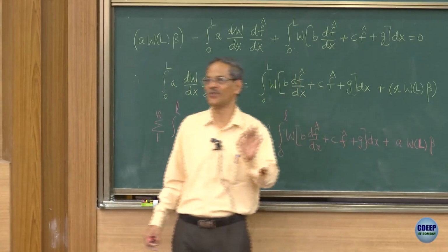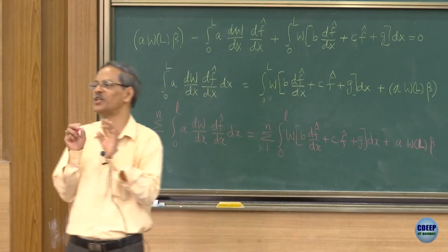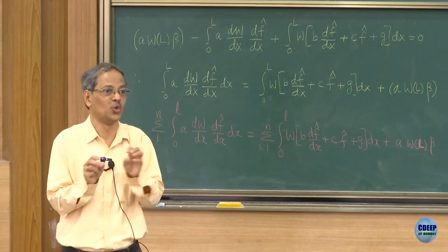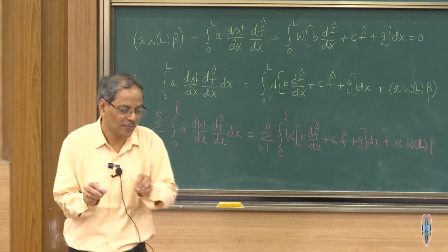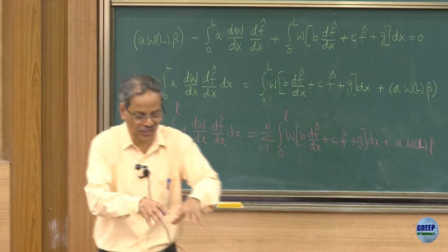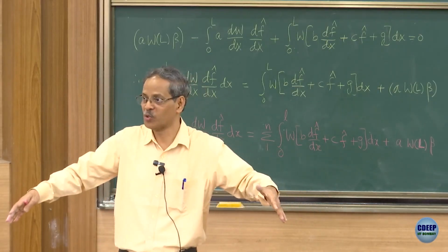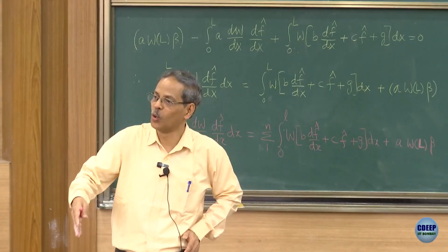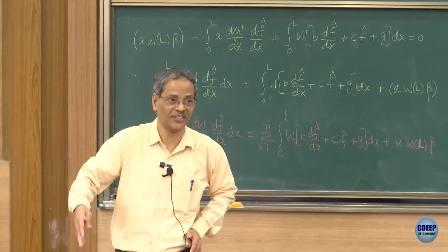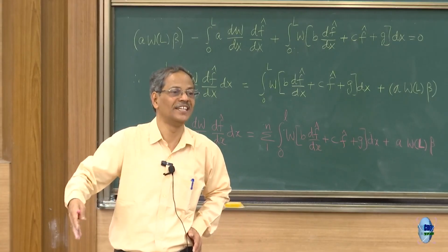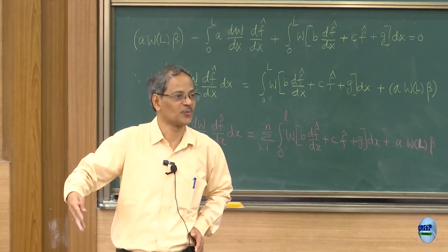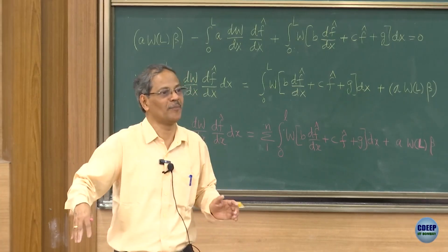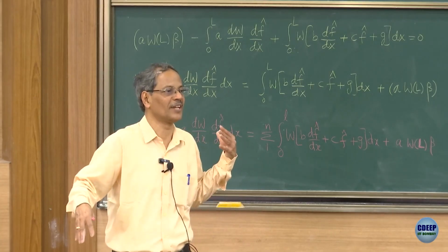What is my strategy going to be? I am going to define this element. In principle, I can choose different types of elements at different locations in the total domain. Supposing I think that there is significant loading happening at a particular location, so there is a strong variation in the displacements and correspondingly the strains and the stresses, which cannot be captured by the linear element trial function.